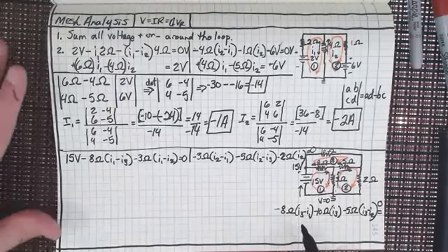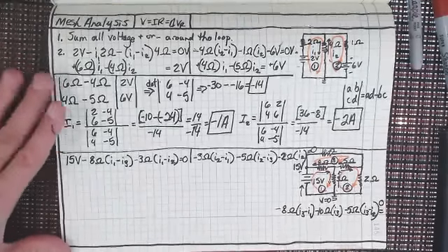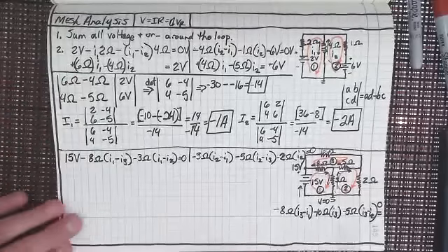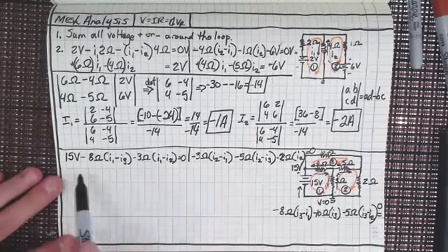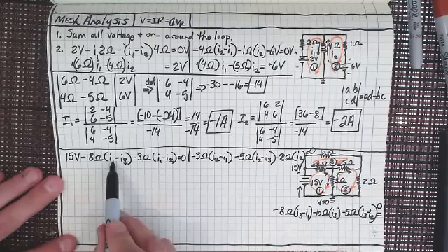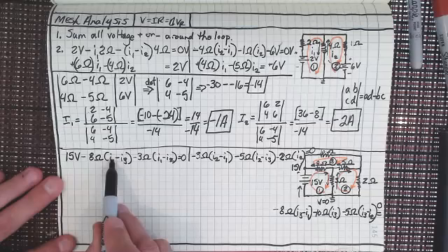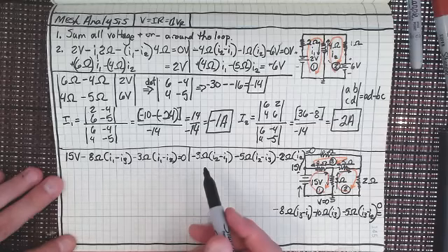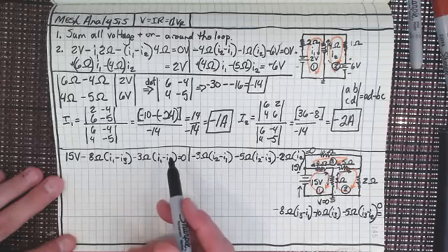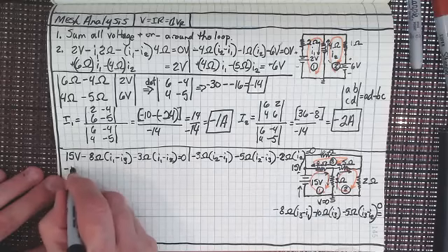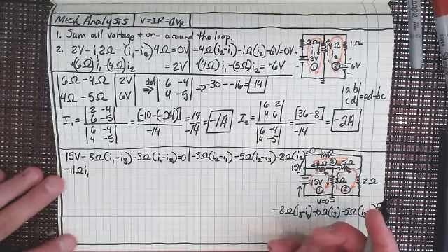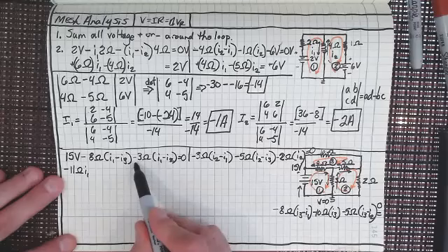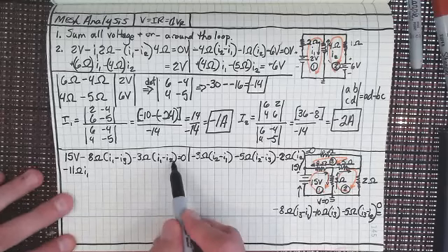So we've got 3 equations now. I want to simplify those 3 equations in terms so that I can put them into a 3x3 matrix. So let's do that with these. So the first thing I want is I1. Everything has got I1. So I've got minus 8 I1 minus 3 ohms I1. That's minus 11 ohms I1. How about I2? I've got minus 3 ohms, and then I've got minus I2.